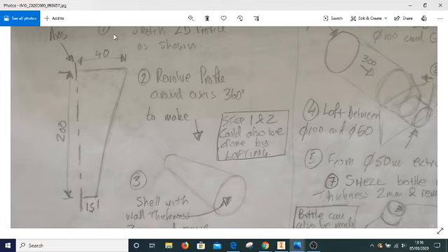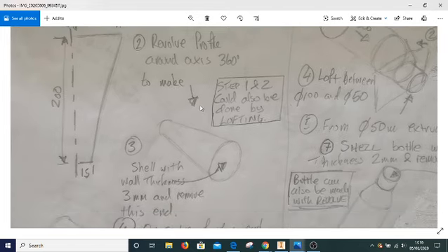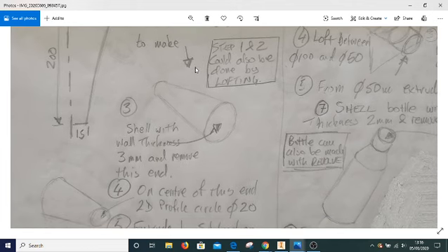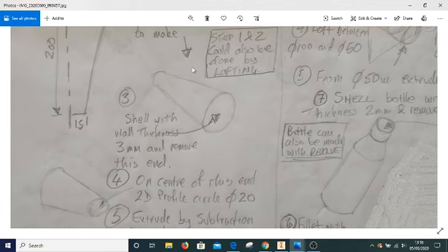Step 2 is to then revolve that profile around the axis for 360 degrees. And it's important to say it's a full turn or 360 degrees, because if you don't say that, then we won't end up with the shape that we're looking for. In my model plan, I've just made that little point that I could have done step 1 and 2 by doing lofting. I could have sketched a 2D profile of an 80mm circle, offset a plane by 200, and then drawn a concentric 2D profile of a 30mm diameter circle, and then lofted between the 2 of them.